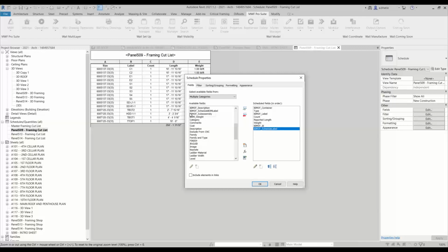But you can see right here that it basically grabbed that parameter from there and dropped it in here. So it would have been the same thing as me just dragging and dropping that. The reason this happened is because the GUID from that shared parameter is the same for the parameter that was in that list and for the parameter that I tried to add in. Okay, so that is there.